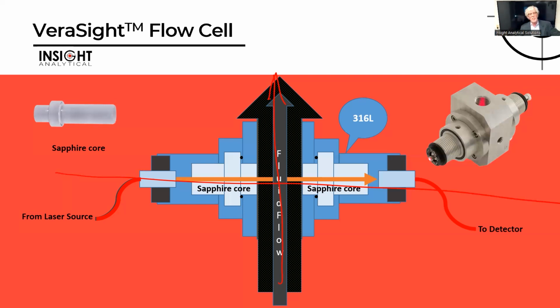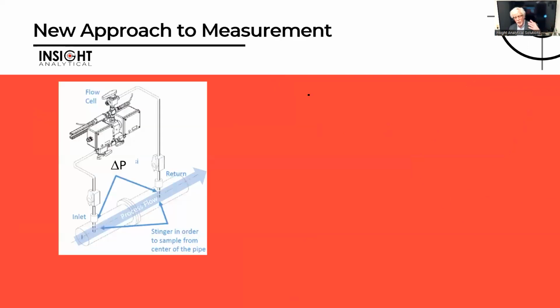With a conventional analyzer, I usually bring a sample out of the process and bring it all the way over to an analyzer building. It can change phase along the way. What we do with this is we mount that flow cell. That's the same cell I just showed you. We mount that out as close to the process that we want to measure as we can. We find some source of process differential pressure, maybe an orifice plate, process filter, a pump.